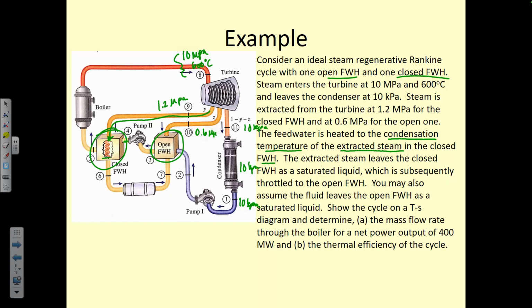So coming out here is partially condensed steam. If it's at a given pressure, this has to be the saturation temperature, Tsat, at 1.2 megapascals. Not a superheated vapor, but a saturated liquid-vapor mixture, because a superheated vapor doesn't have a saturation temperature. Only mixtures do. Okay, confusing, right?